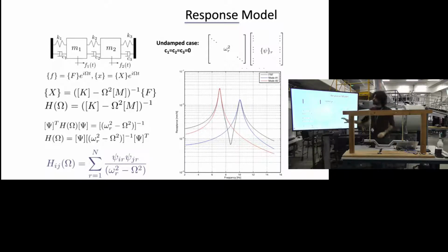Finally, as I said, you can also bunch the solutions up. You can sum them up. Say this is solution 1 of the modal model. Remember, a single degree of freedom system has a single peak, and the second modal mass vibrates with this other peak. If you sum them all together, you'll find this is the frequency response function of your physical problem. So that's very intuitive and also very easy to visualize.